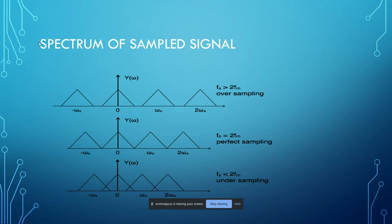In the second one, we clearly see that the sampling frequency is exactly equal to two times the maximum frequency of the signal. In this scenario also, we are not encountering any type of aliasing effect. When the sampling frequency is lesser than twice the maximum frequency, that means an undersampled signal, we are going to see some aliasing effect in the signal spectrum. It causes loss of information at the time of reconstructing the signal. So this is the main effect we see whenever we take the sampling frequency less than twice the maximum frequency.